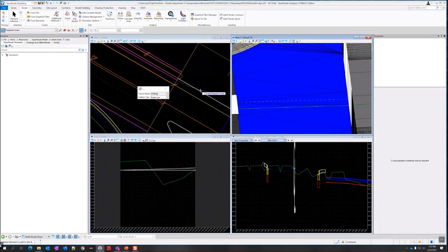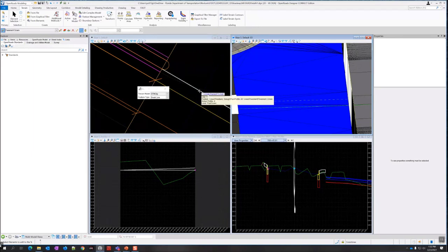So the other ones we added when we created them, we added them all as boundaries. So I'm just going to select this pavement crown line and then reset. You can add more than one line at once if you want. I'm going to accept that break line. And notice the triangles changed in this area.